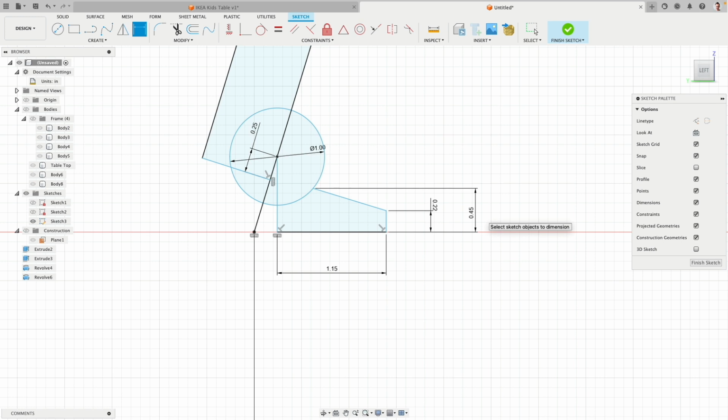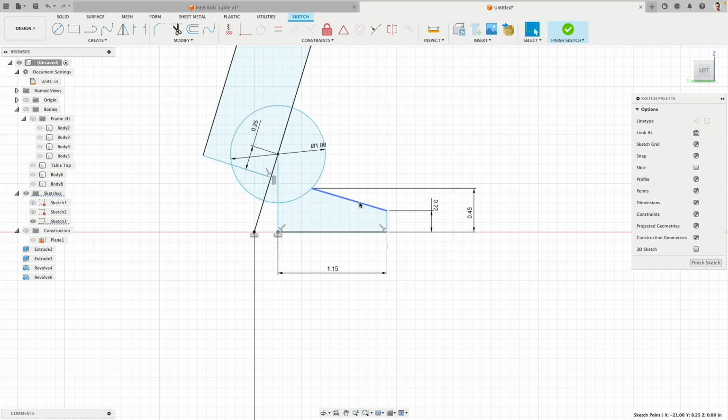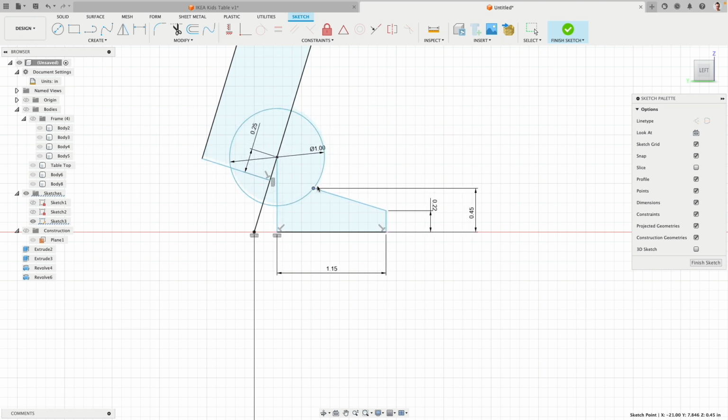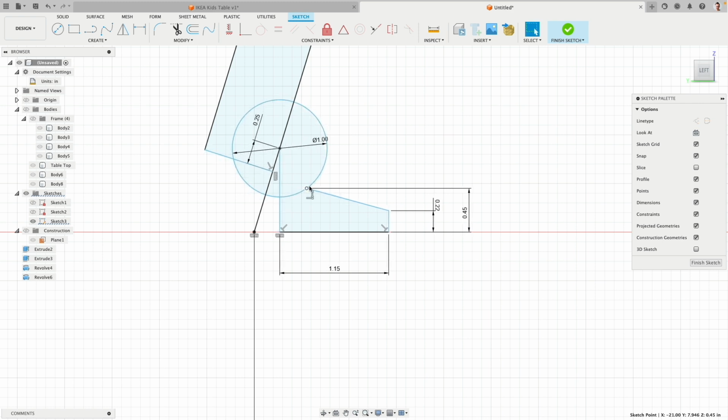And actually now you see that this is still moving a little bit crazy. Why does this happen? You see where this is rotating around. Now it's sliding on the circle. We can go ahead, select 2 lines, and then add an angle in between. Let's say 105 degrees. Very good. Perfect.